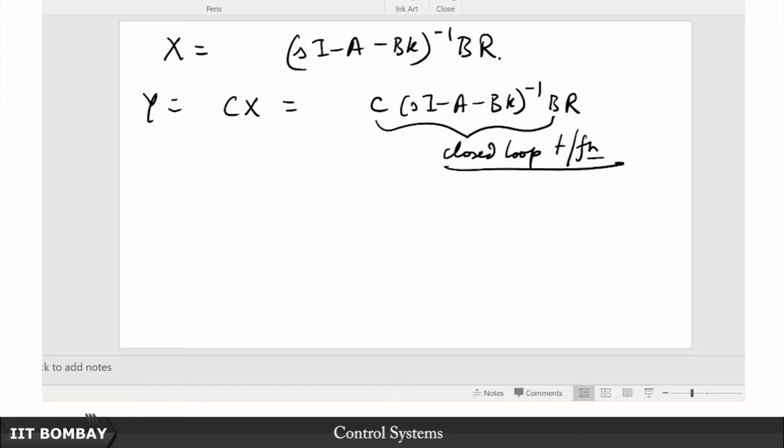Be aware, however, that shifting the zeros of the closed loop transfer function still remains a problem. If you are not convinced that the zeros cannot be arbitrarily placed even if your poles can through state feedback, here is a little bit of an explanation. I do not want to leave you with the impression that all the problems have been solved. There is still this problem that you cannot place the closed loop zeros, although you can place the closed loop poles, well, at least not independently.